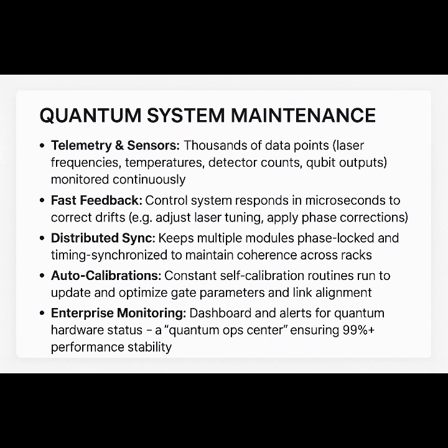A 2.3 ms latency suggests an FPGA-level control rather than a high-level software, or at least highly optimized code paths, perhaps on a real-time OS. Possibly, they offload critical feedback to FPGAs, or even custom ASICs, while higher-level decisions, like Bayesian estimation to refine parameters, run in software slightly more slowly.